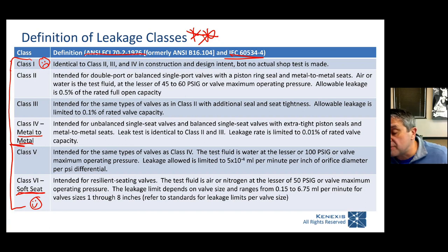And that's ultimately what is going to provide that leak tightness, a very tight interference fit between the moving surfaces. But if those surfaces are metal to metal, if that fit is extremely tight, well, then you suffer because the valve won't be able to move.